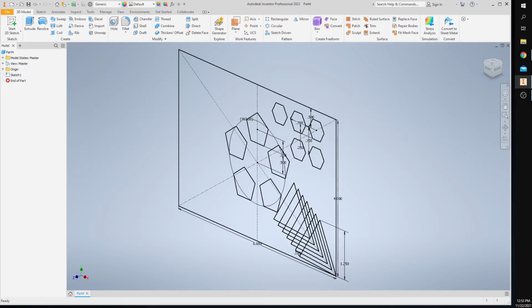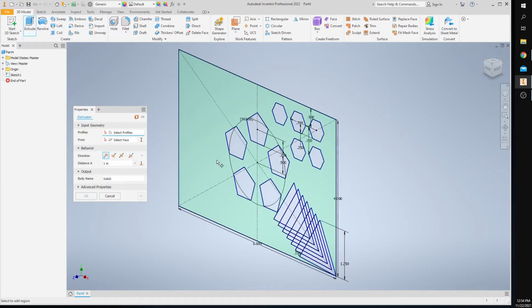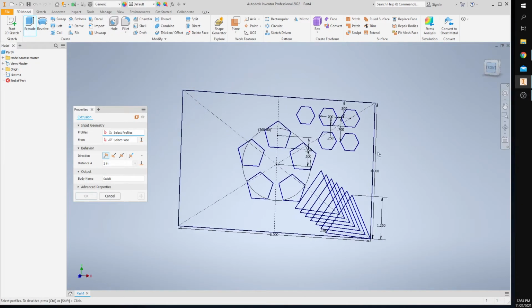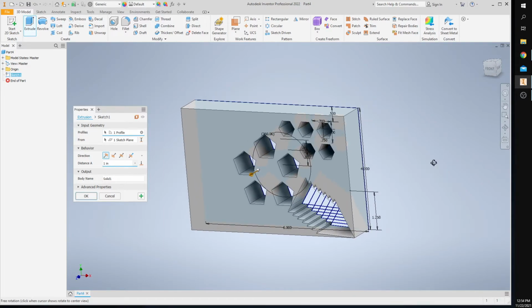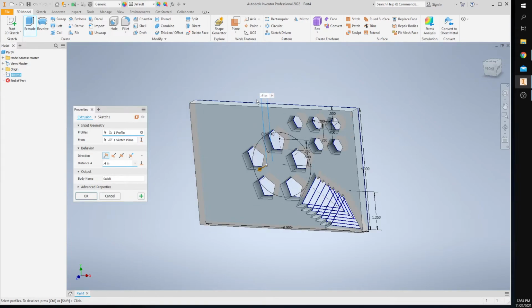Estimate the extrude distance and extrude the appropriate sketch shapes to obtain a model that resembles a flat plate shown in figure 7. So let's go ahead and extrude. Okay, so extrude. I'm gonna use the front view. I'm gonna go ahead and put 0.4. Again, from the side, if you wanna switch over to the side, you can see that's a little too thick, right? So I'm gonna type in 0.4. There we go. And I'm gonna keep going,